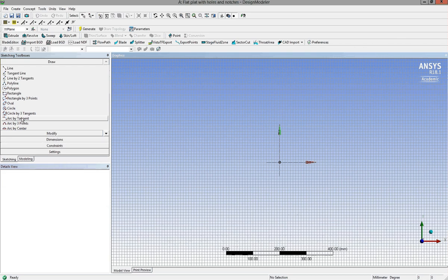So if I now go into draw a rectangle, so in the draw there's lines, rectangles, circles, etc. So we can pick a rectangle, and we now get this drawing, the pencil icon or pen icon, and down in the bottom right hand corner it gives you the current coordinates of the pen. So as we move the pen, you can see there it's changing, -490. So I want to go 500. I'm going to use the origin of the axis as the center of the plate. Okay, so I want to come down to 70 millimeters.